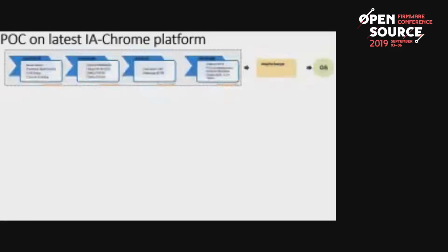So here's your classic Coreboot boot flow, which probably everybody in here knows by now. There's your boot block, your ROM stage, the Postcar where you tear down cache-as-RAM and do some MTRR stuff, and then RAM stage. And this is a heavily FSP-centric slide, as you can see. This is not your grandfather's Coreboot, because there's just a lot of binary blob action in here with the FSP. But that's how it's done on newer Chromebooks today and other platforms. And here's some rough size numbers.